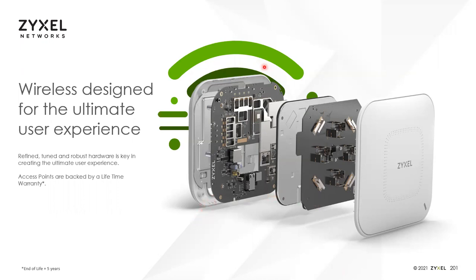So one of the things you'll notice is our external housing has a lot of vent holes for heat to release. So when you're dealing with solid state devices like this, one of the leading causes of failure is heat fatigue over time. So basically the heat cycling, the heat buildup in the devices can cause the chips themselves, the little micro switches in those chips to fail. It can also cause solder joints to fail. So we've got vent holes to make sure heat can get out. And then you will find on most of our APs a large metal, essentially a heat sink designed to draw heat off of the board and vent it out those holes.